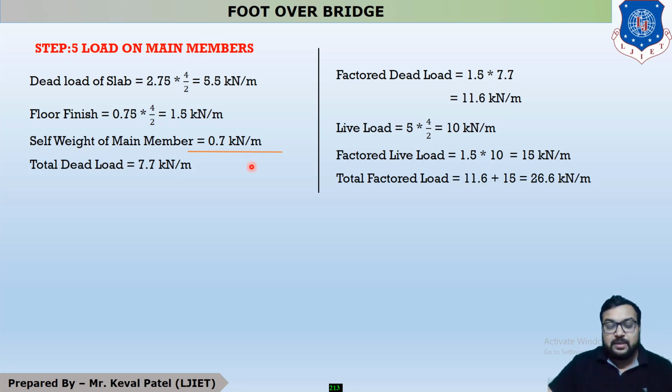So students, in this example you can see that we have to calculate the dead load and live load separately. Why? The reason behind calculating dead load and live load separately is that we can design the vertical members and diagonal members. At that time some members are designed for compression and some for tension, so we have to calculate the loads, dead load and live load, separately.